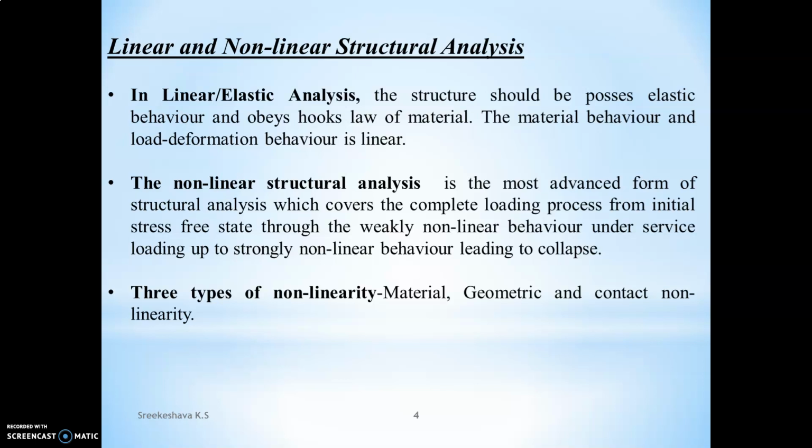But another form exists, that is the non-linear structural state, in which the most advanced form of analysis can be done. Non-linear structural analysis covers the complete loading process from the initial stress-free state, through weakly nonlinear behavior under service loading, up to strongly nonlinear behavior leading to collapse. So from the initial stress-free state to the final collapse of the structure, we capture the behavior in nonlinear structural analysis.